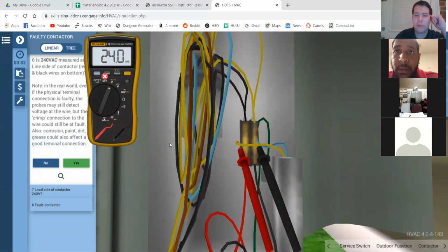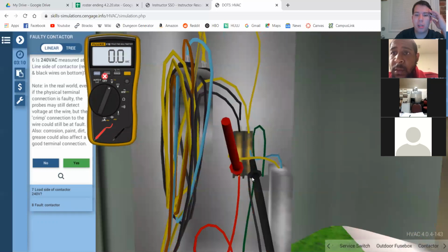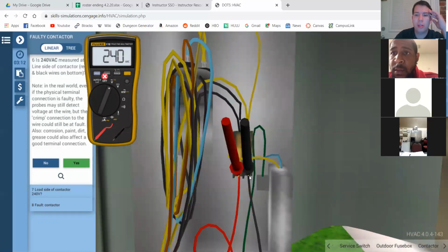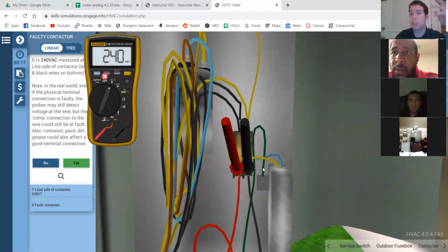So that's right as far as the control side of it. The only other connections on that contactor are 2 connections on the bottom for high voltage power coming in, and then high voltage coming out the other side of the contactor. Just like a relay, remember earlier when we had that relay where we checked the 24 volt coil, 240 coming in, 240 coming out, we're doing the same thing with the contactor.